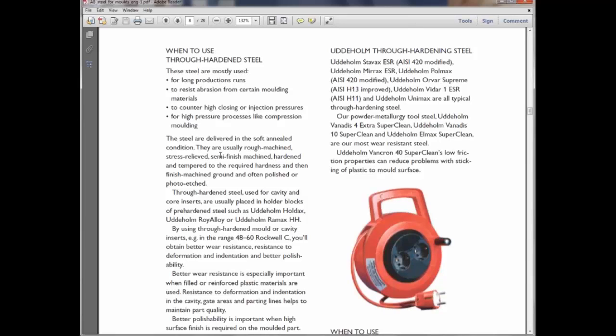At that time the load on the cutter is very high, because we are taking a very big depth of cut like 0.5, 0.6 mm.